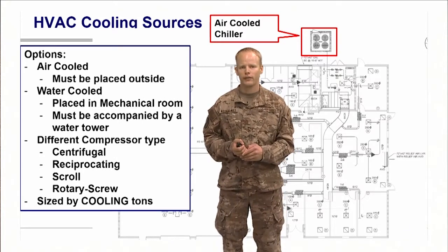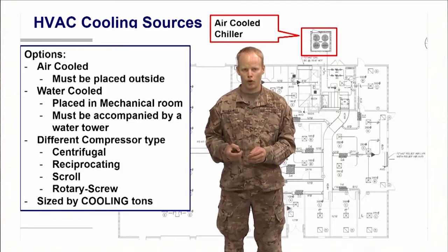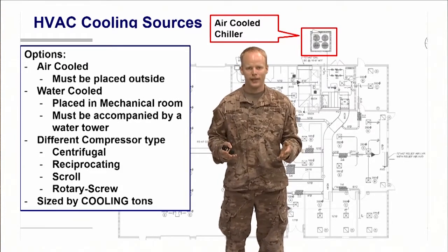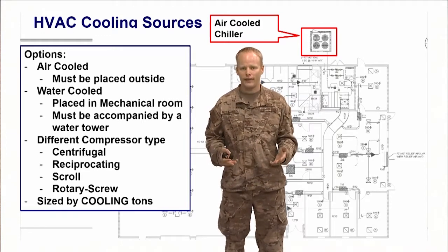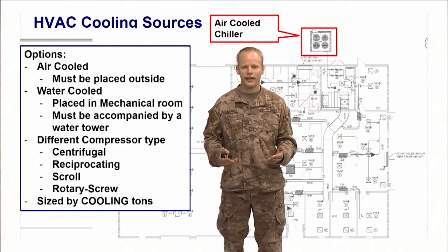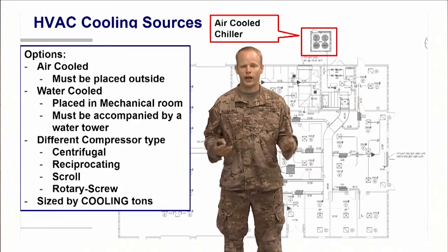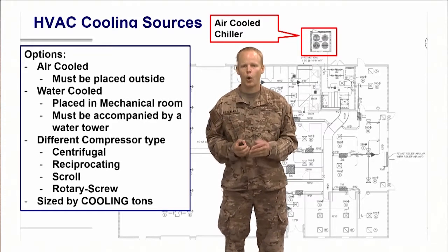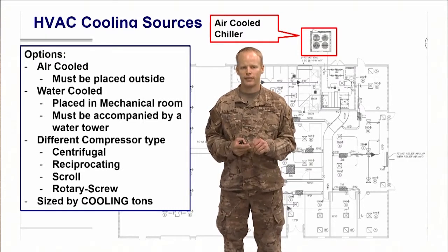And then you'll have different compressor types: centrifugal, reciprocating, scroll, rotary screw. So looking at this drawing set, I can't tell you what this is. You're going to have to find that. If you're the mechanical engineer doing the design, you're going to be speccing that out yourself. If the contractor hasn't told you what type they want to put in here, reach out to them and ask that question, or it will be listed in a schedule somewhere. So you'll have to find that and size it off of there.